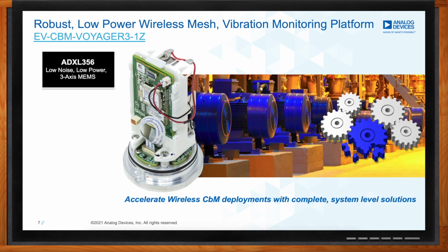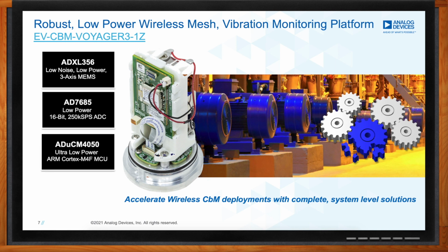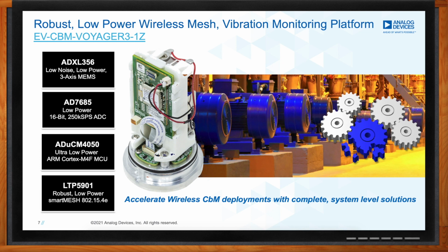It comes with a proven mechanical mounting stud at the bottom so that it can be mounted directly onto the asset. From a sensing perspective, it's based on our ADXL356, a very low noise, low power, 3-axis MEMS sensor, coupled with our low power ADC technology. It also features the ultra low power ARM processor to process the data, but most importantly, is based around a very robust, very low power SmartMesh connectivity.